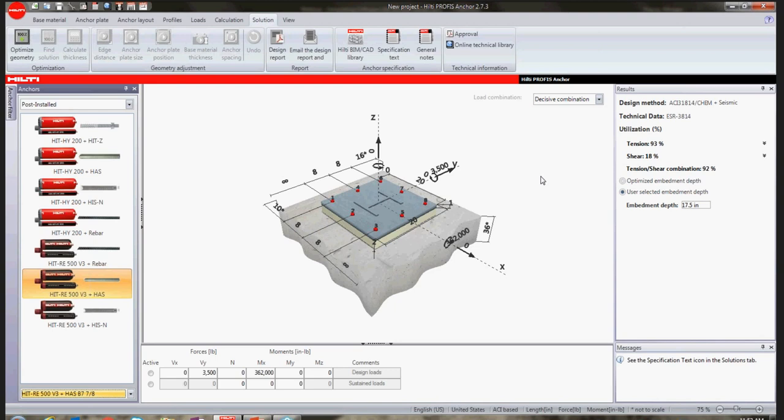we're getting a note on the screen. Why are we getting a note on the screen? Because it wants to make sure that you have taken into consideration the omega naught factor in the ASCE. Okay, so when I input these loads, I'm already going to assume that I've